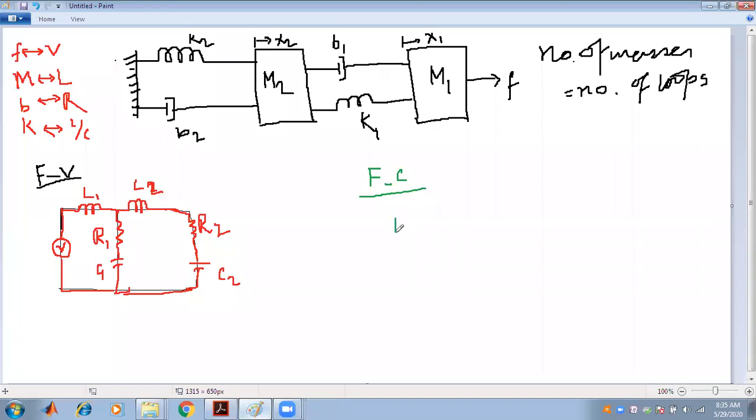So first I draw the voltage, which is replaced by the current: V is replaced by current I. Then L1, which is connected in the series branch, will go to the parallel branch, and L is replaced by a capacitor C, called C1. And again this series branch will be replaced by a parallel branch.